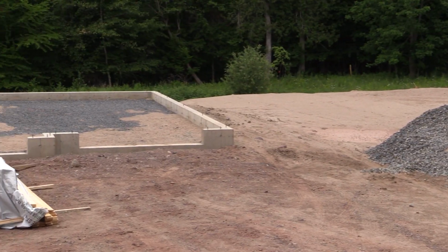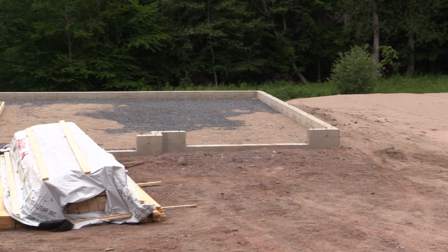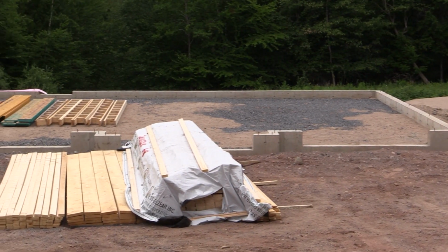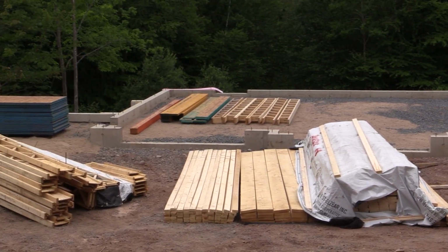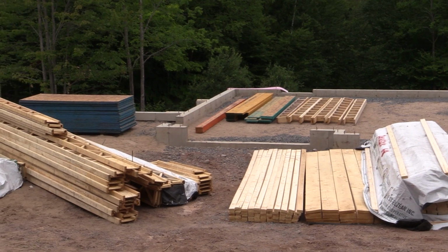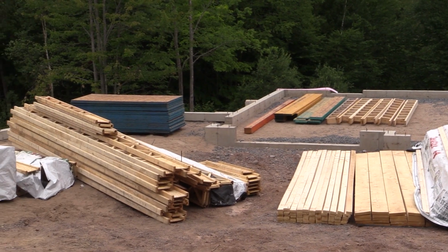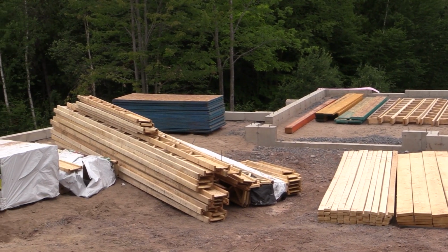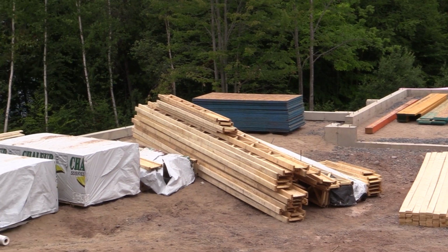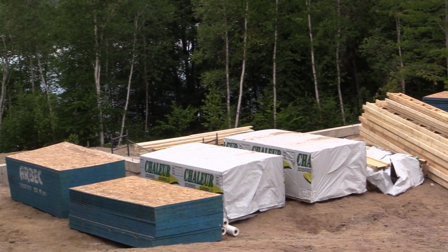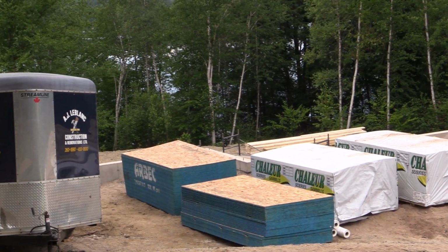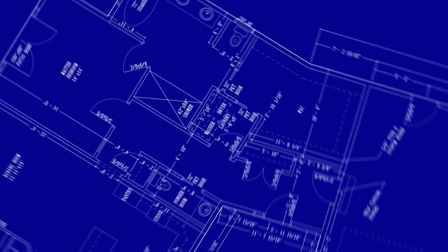All of these building materials were manufactured using imperial dimensions. There are 2-inch by 4-inch studs, known simply as 2x4s, as well as 2-inch by 8-inch boards that carpenters call 2x8s. We also have sheets of plywood and oriented strand board, or OSB, that are 4 feet wide by 8 feet long.